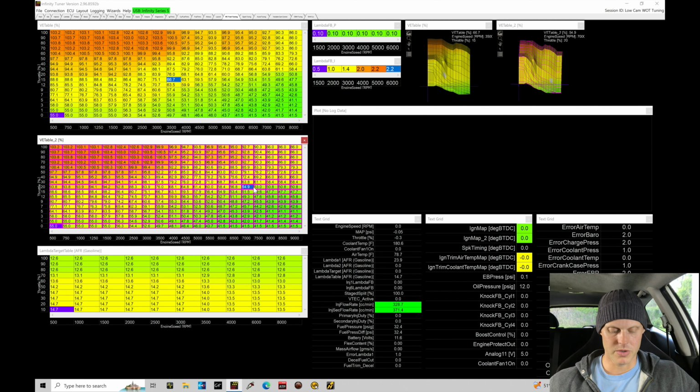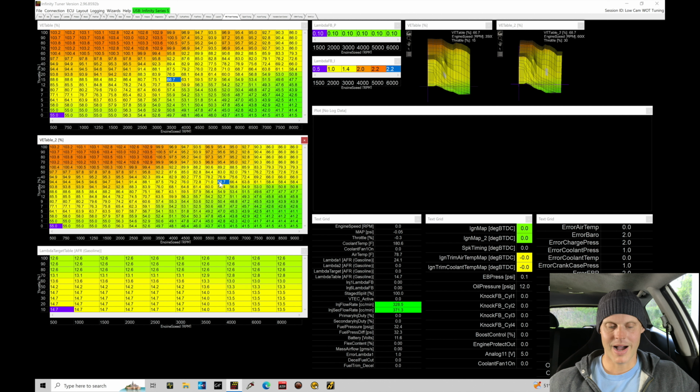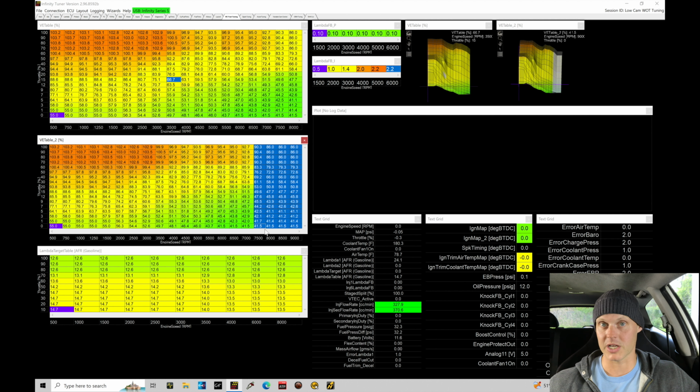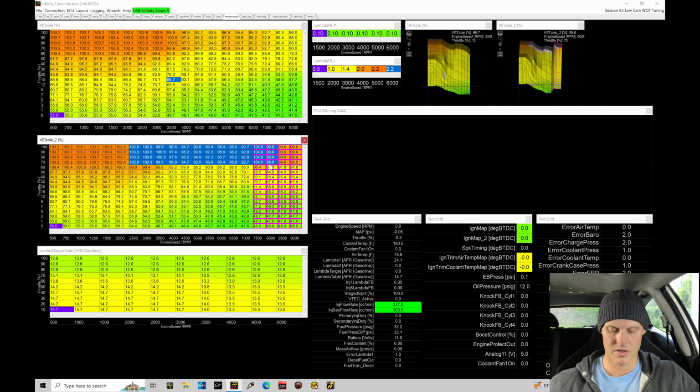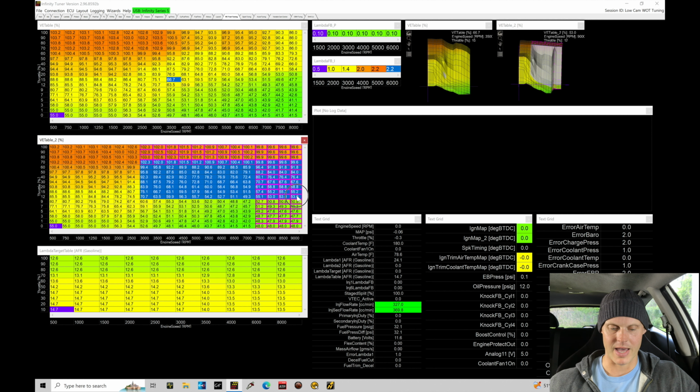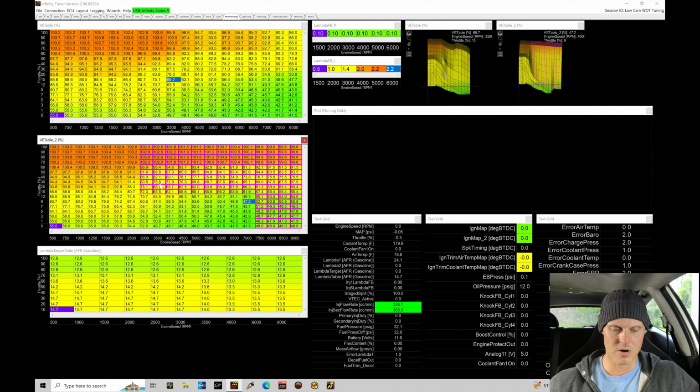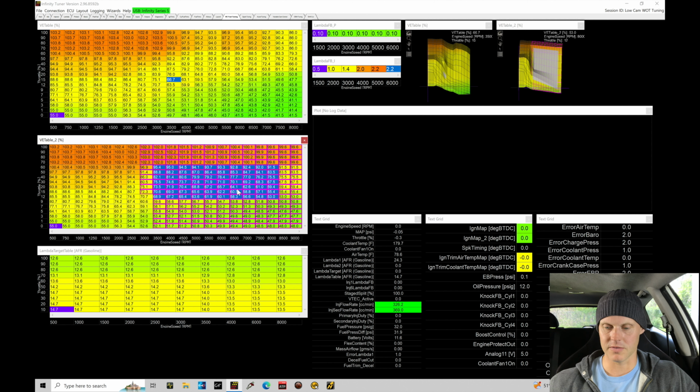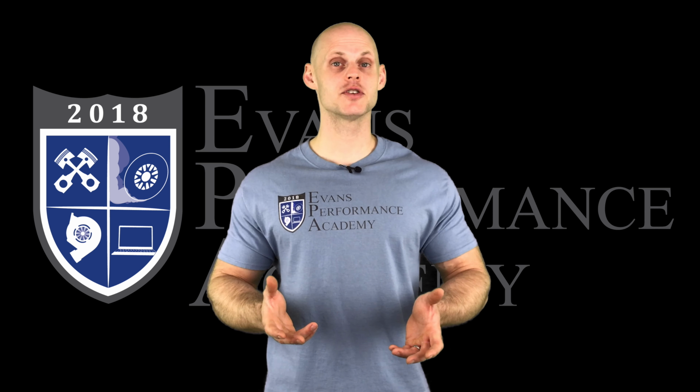Now, what we're going to do here, a little bit of cleanup work, I'm going to add some more VE values on the top end of this table. I'm anticipating here that we're going to have a higher representation of airflow because again, we're locked on that high cam, we're moving more airflow, we're going to make more horsepower and torque out of the engine. I'm going to use Shift Plus and just bump this up a little bit, and then I'll just do a horizontal interpolation across here, just kind of building out the table ahead of time. I don't know if this is going to be what we need for our fueling, but I'm going to take my best guess at this and just do H, blend this across, H and V, just blend this across, and we'll determine where we need to be at. Let's undo that change.